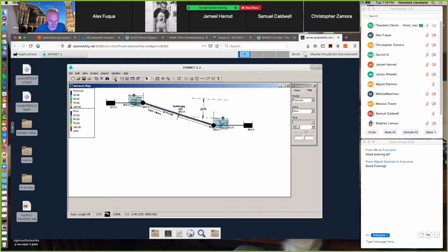So I press the lightning bolt and we wait and we get the most wonderful output from a computer program that you could ever hope for, which was the run was successful. What that means is that whatever input we gave it, it was able to make calculations and produce results without generating any warning or error messages. Doesn't mean it's right yet. We still have the obligation as designers to check the results and see if they make some kind of sense.